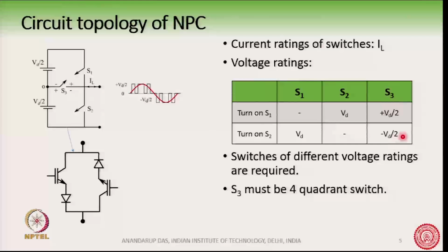So, this is what is shown here, that S3 needs to have plus Vd by 2 and minus Vd by 2 as the bidirectional voltage capability.